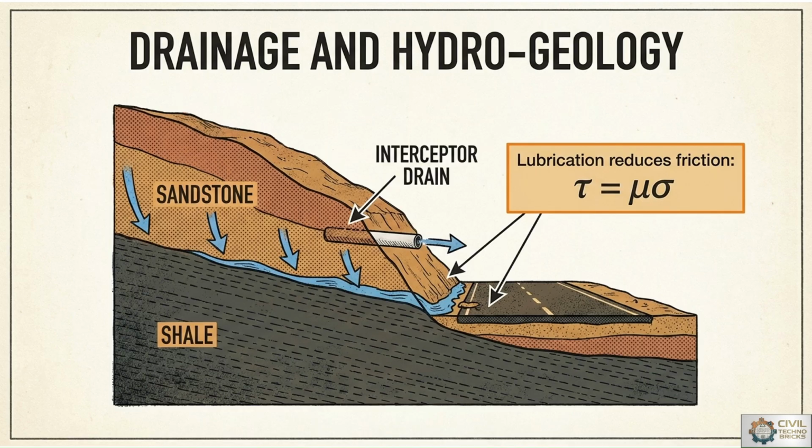With reference to that damage, geological investigation identifies suitable construction materials such as aggregates, sand and stone. Quality of material improves pavement strength and durability. Nearby material sources reduce transportation cost and project expenses also. So unstable materials may lead to premature pavement failure. Material testing is required, which ensures compliance with highway engineering standards.